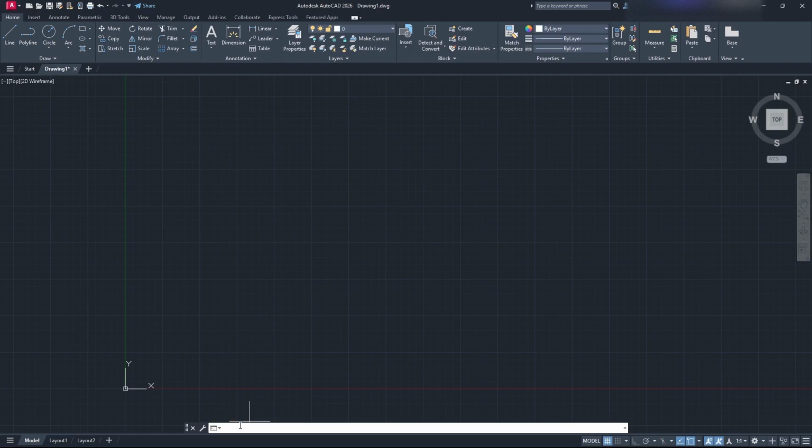Once you see that command pop up, press enter, and it's going to ask you to enter a new value. If yours does not say 3 in those little brackets, you can see right here, mine says 3. You want it to say 3. So if yours doesn't say 3, press 3 and then press enter. What that does is it allows you to have your command bar show up when you're just typing. So instead of having to go down to the command bar, type in units, press enter, and open it, I can just start typing, and it's going to have that command just show up for us right there.